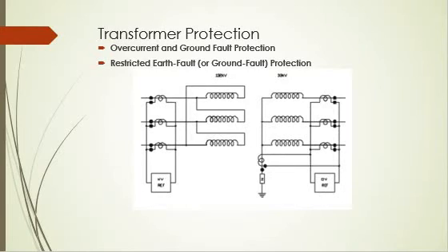When one transformer trips, the total load is then carried by the transformer remaining in service. This can result in emergency overloading of this transformer of say 150%. It may be possible for the transformer to tolerate this emergency condition for about say 2 to 3 hours, providing a winding temperature of 105 degrees centigrade is not exceeded. During this emergency overload period, load shedding or load transfers can take place to bring the transformer load down to the nameplate rating before the windings become overheated. An overcurrent pickup setting of twice full load is often used to allow for this emergency situation.